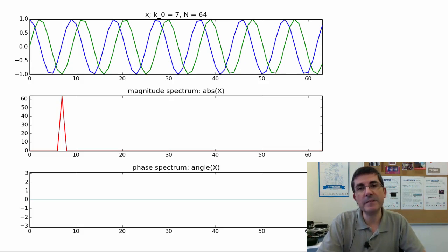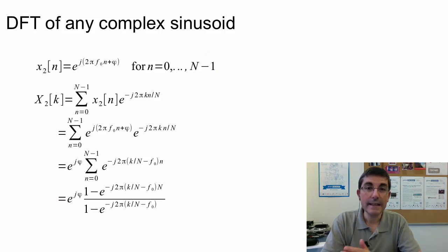However, this is a very special case in which the complex sinusoid is one of the basis functions of the DFT. This never happens when dealing with real signals. Let's see a more realistic example: the DFT of a complex sinusoid of any frequency.